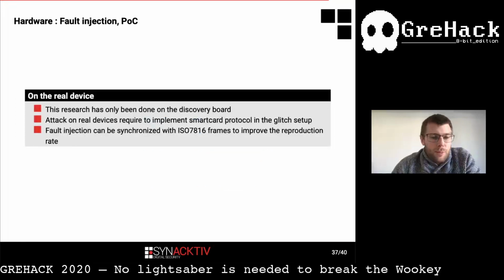To conclude on this part, we only did the attack on the discovery board. On the real hardware, we have to implement the smart card protocol in our fault injection setup. On Wookey, we think that we can improve the reproduction rate by synchronizing the injection with the smart card frames.